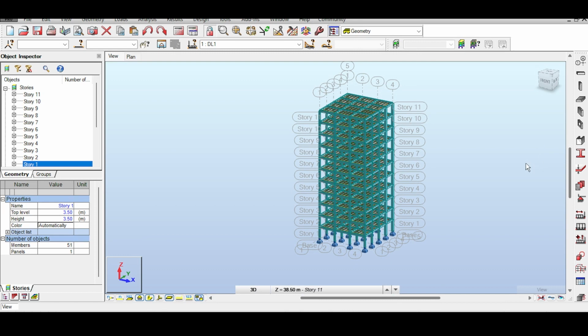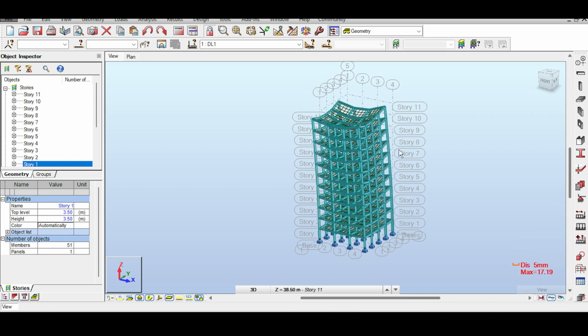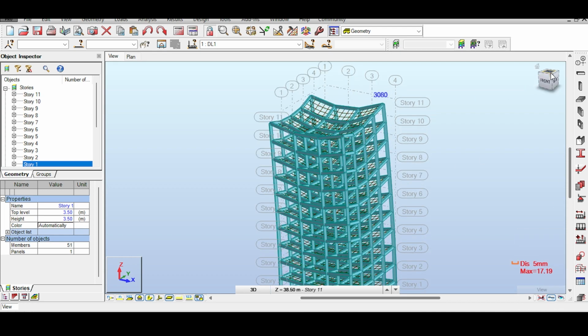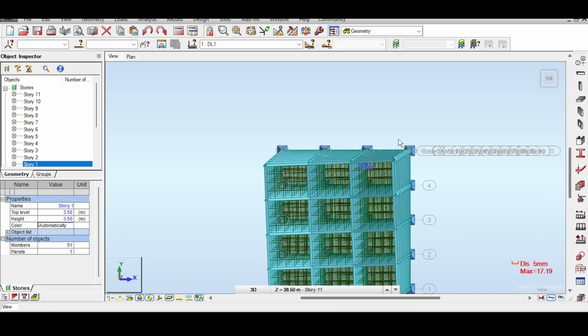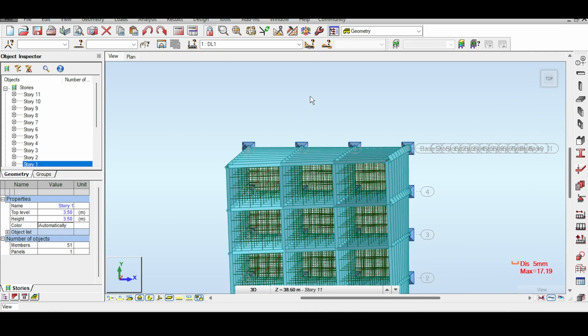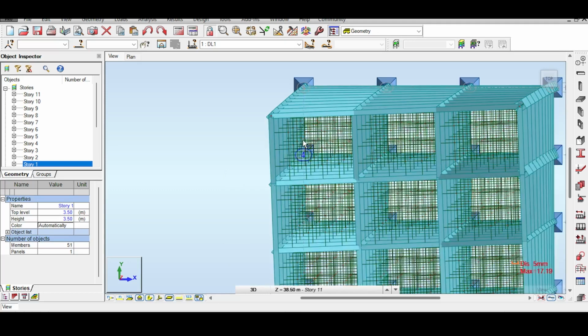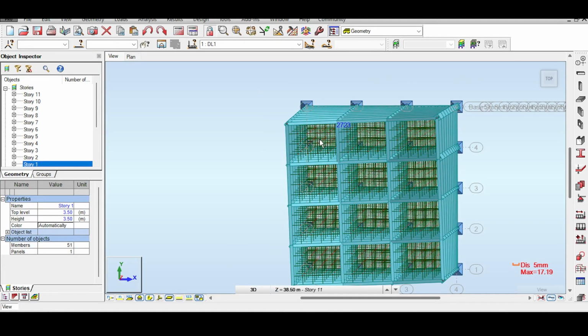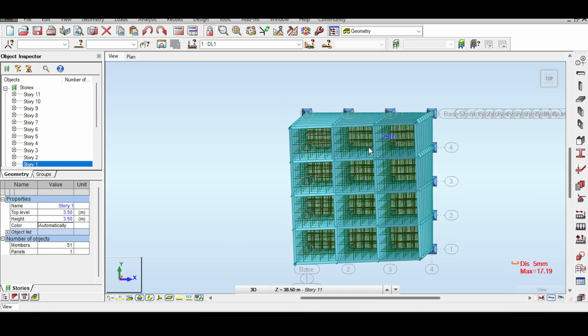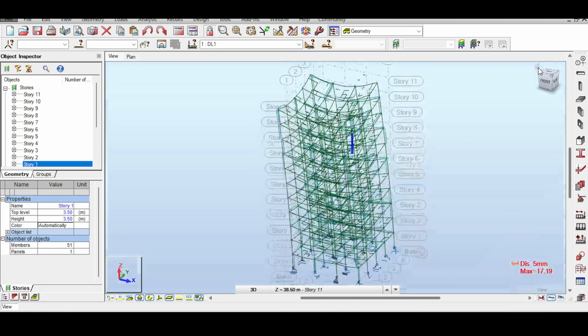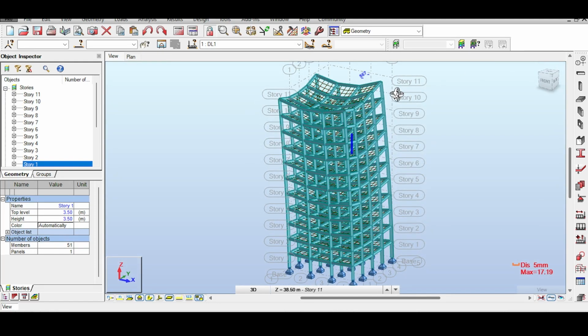Okay, moment of truth. Clicking on this, you will see leaning towards the camera and to the left, and you can see it happening here. The tower, if I go to top, you can see the leaning clearly. The tower is leaning to the right and leaning down, and you can see some twisting motion that can be compounded later, but the idea is that this unsymmetry of the load-carrying elements makes the structure lean.